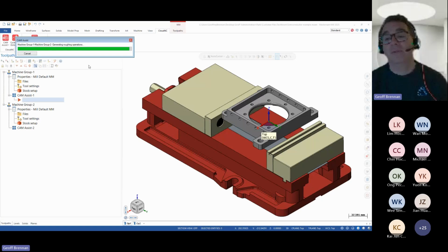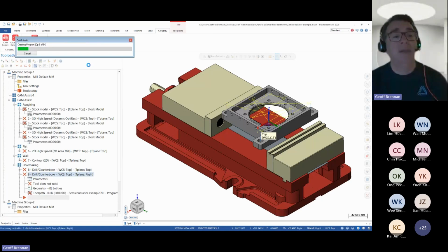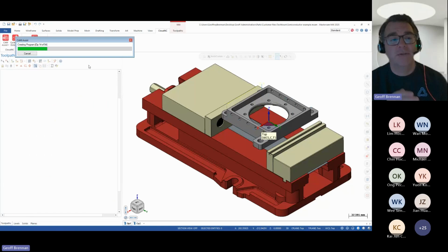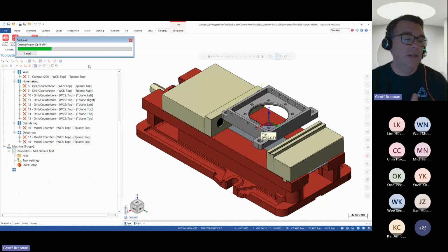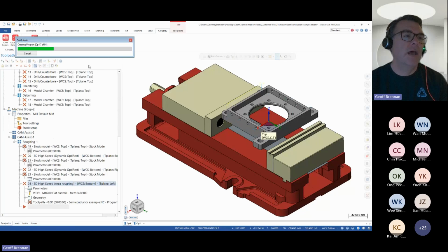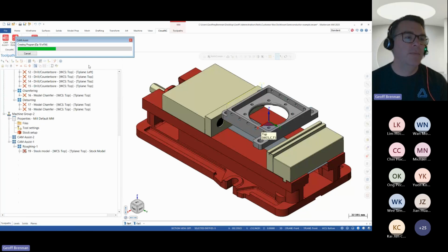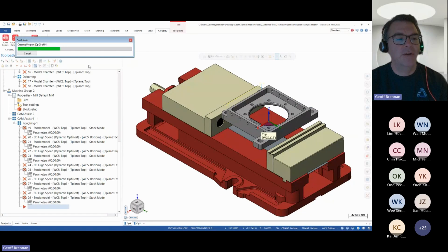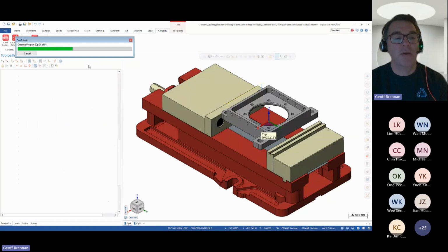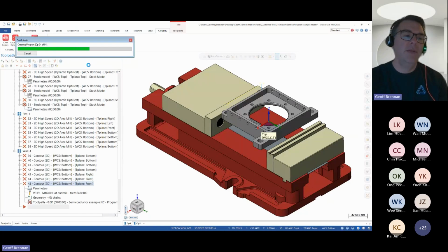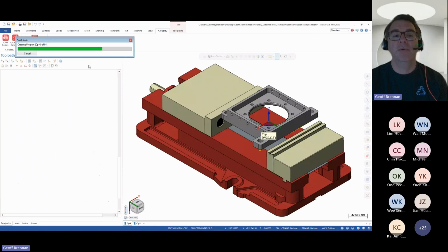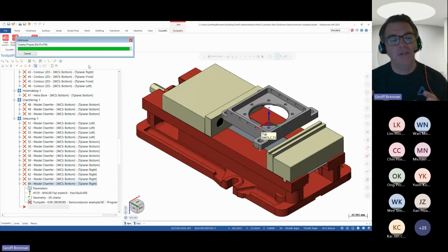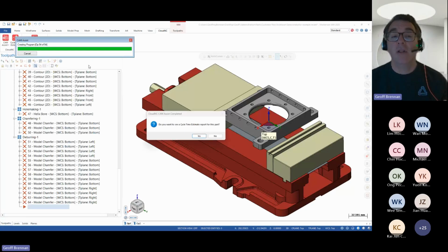As we map into, say, roughing, we create roughing toolpaths. So you can see now on the left that the toolpaths are coming in from the cloud, and they're coming in dirty, which is fine. And we're going to have 54 operations coming in for this part. There's going to be more operations in the toolpath groups that are defined, because we do add some stock models when we do roughing. And we use the roughing stock models actually to compute the next step in the roughing process. So basically, Cam Assist takes the part from the finished state, breaks down all of the different elements of the part back into the roughing state.